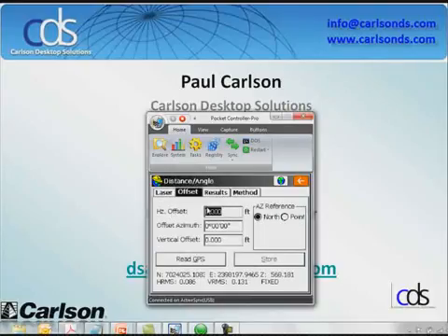If I did a standard offset, I'd say, here's my current GPS position, go ahead and read my GPS position, so it gives me the position, and I tell it to offset 100 feet at a 45-degree azimuth, no vertical, and I tell it to read again. Now I have a new position, 100 feet at 45 degrees from my current location. The elevation, which was the other question here, is projected. So it doesn't know what the terrain is doing. It's not going to interpolate and try to figure out what the ground is doing out there. It's a straight line projection. So I probably wouldn't do a 100-foot offset because your elevation is most likely going to be off.